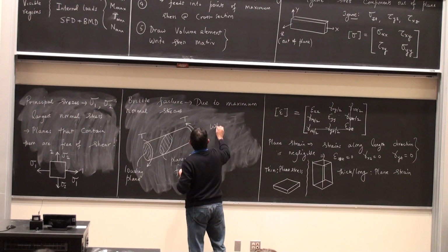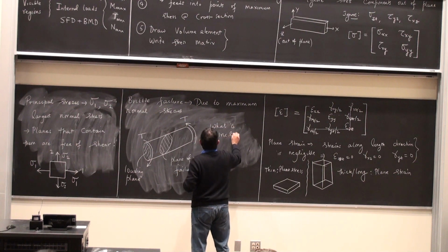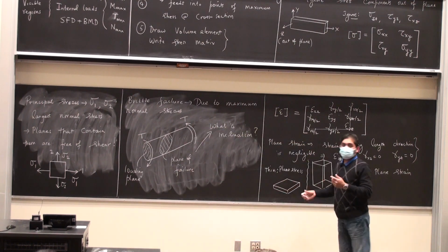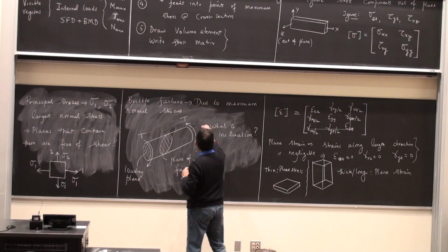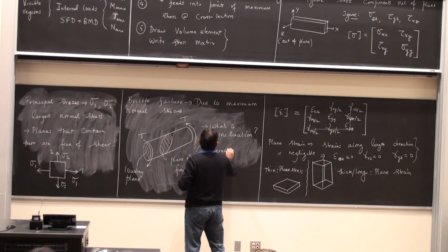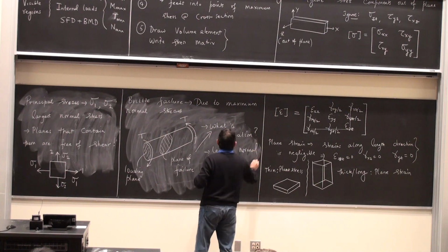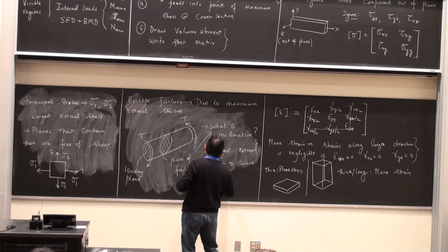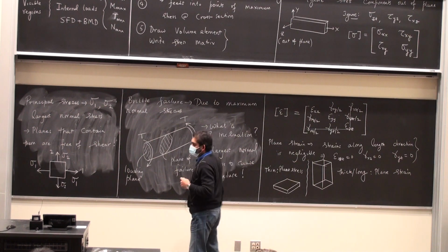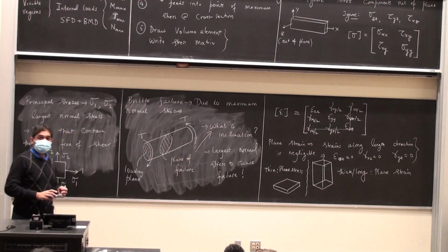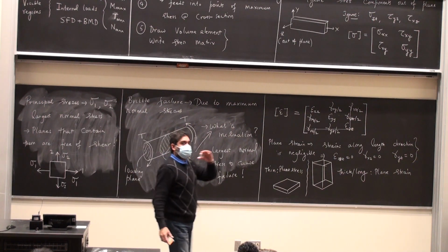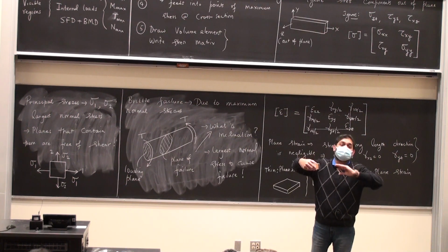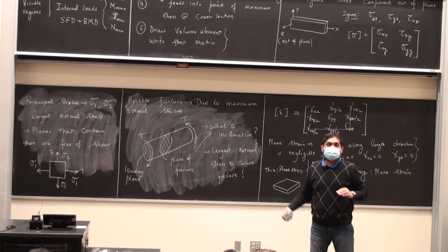So what is the inclination? And what is the largest principal stress value or the normal stress value to cause failure? We want to figure these things out. So everybody agrees with me that the plane of failure of the brittle material, if I apply a torsional loading, is an incline. You can also break a couple of chalks after lecture.